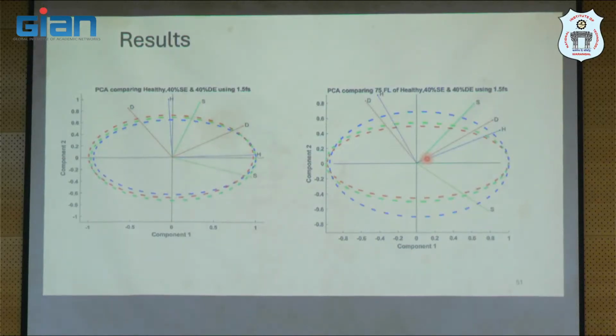Concept-wise, principal component analysis is very intense. For our application, since I am only using a two-dimensional feature vector, the alpha and beta axis currents, it is very much simplified, and that seems to be giving us a trend in classifying whether the system is healthy or faulty. So this is the idea of applying principal component analysis to the given data set to segregate between a healthy condition and a faulty condition.